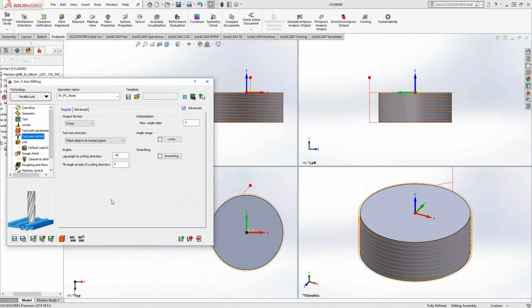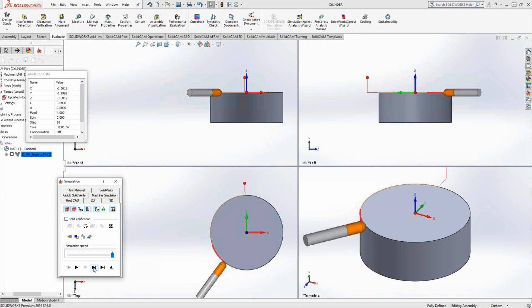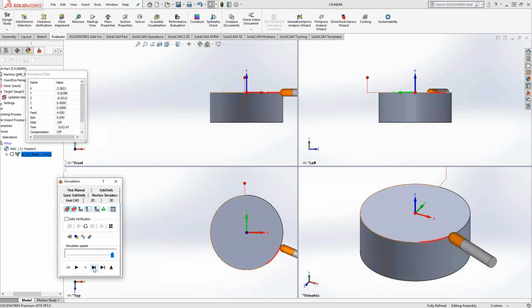section. By default, it will be at 0 degrees, which means that it will have a toolpath that basically looks like it's perpendicular to the surface. And as it goes along, it maintains that perpendicularity, as you can see in the various views we have on the part here.